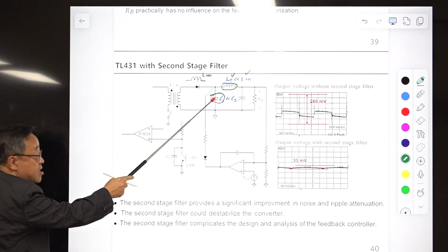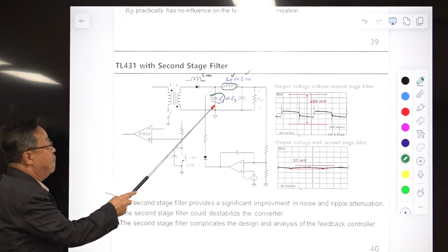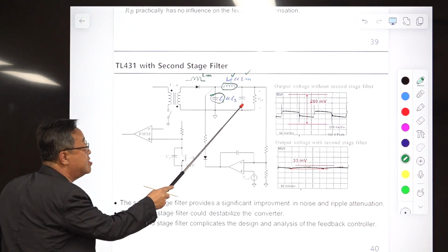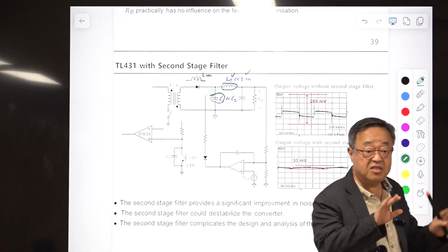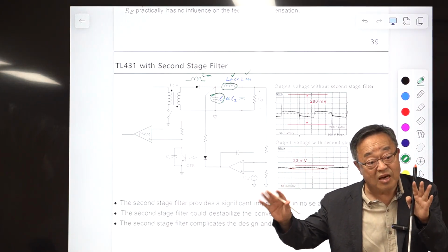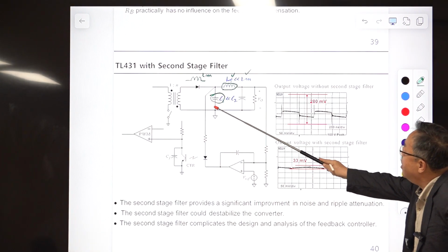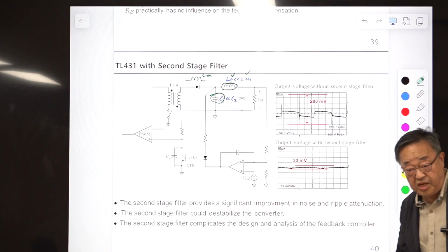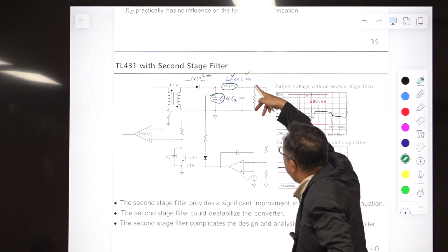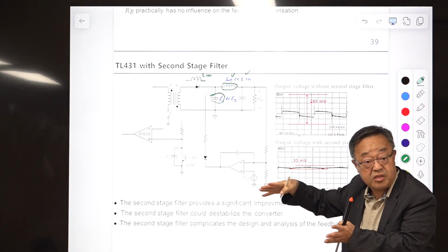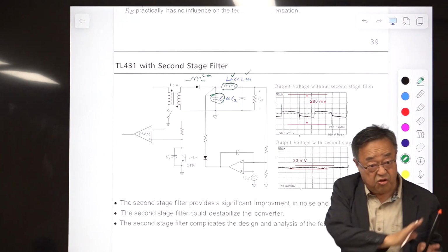Okay, before this. Okay, in terms of the circuit property, it really doesn't matter whether this comes first and this comes last, or vice versa. In this case, the transfer function remains the same. The transfer function is not dependent on the order of components, okay? But the benefit of using this is, if the small capacitor is here and the larger one is here, you have the same waveforms, but somehow you have some parasitic capacitance connected here. There is some parasitic capacitance. Then the parasitic capacitor will be merged with this, then it will disappear.